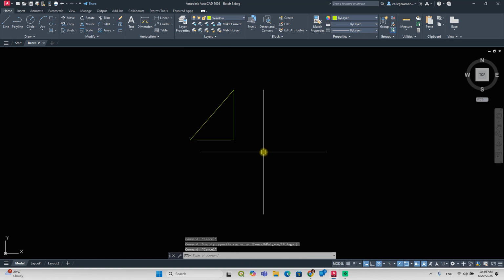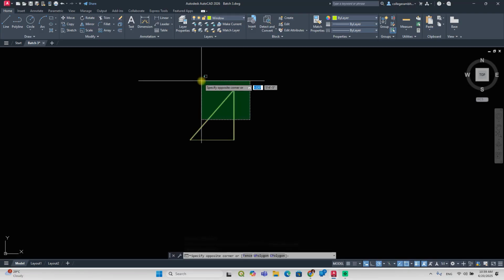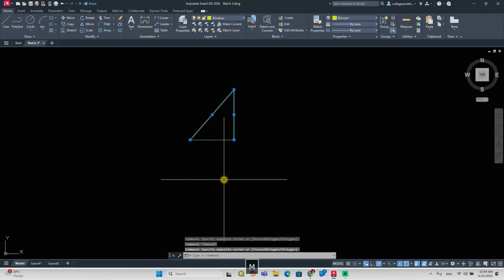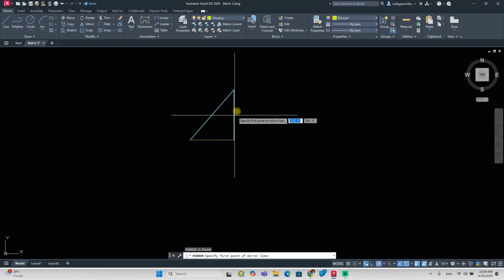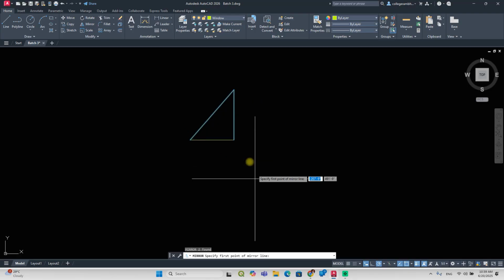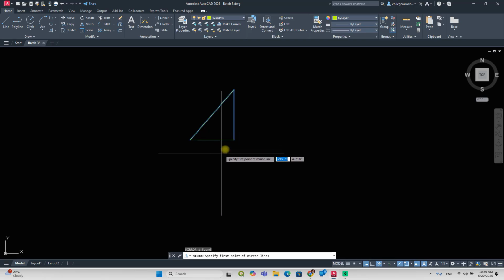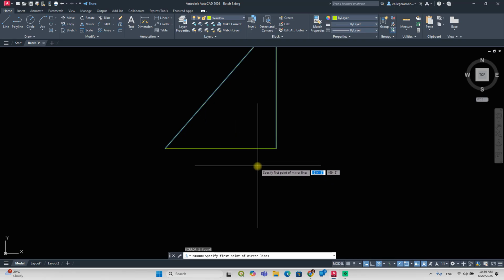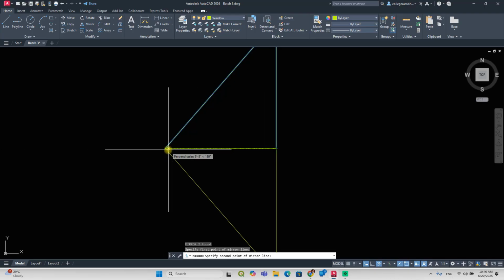This means you need an axis to mirror a line. For now, let me select these two lines and just type in MI and press enter. Now select this axis to mirror these lines towards the downward direction. You have to select the axis, 2 points on the axis. One point is this, just click on this point, and another point is this and click on this point.